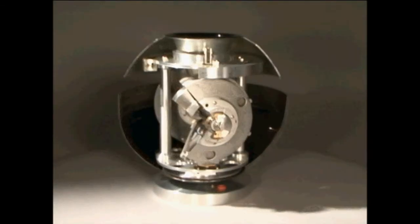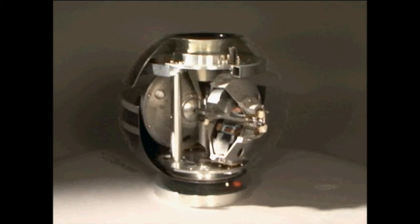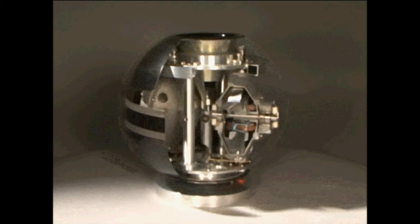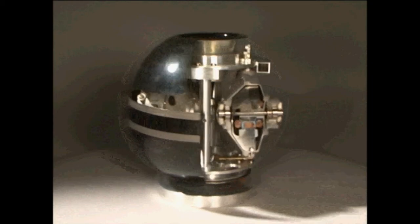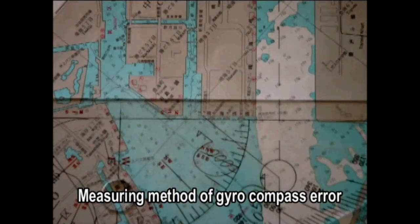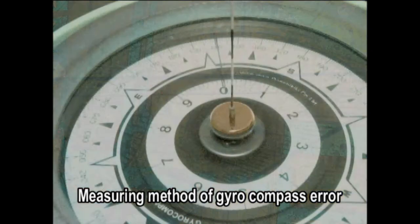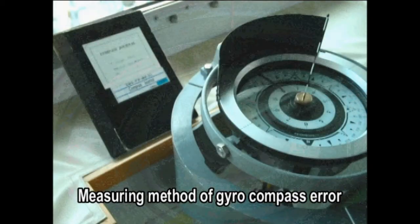The ship is constantly shaking due to rolling and pitching motion. This motion increases the gyro compass margin of error. One solution for this problem is to use 2 gyro rotors. One method of gyro compass error measurement is the amplitude method. The other is measurement using the azimuth of the ship's berth. Gyro compass errors should be measured at regular intervals and the measurements recorded.